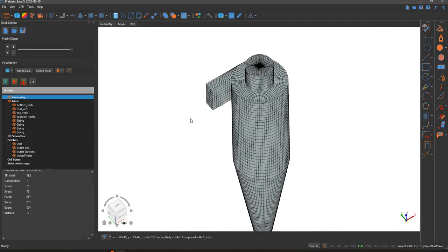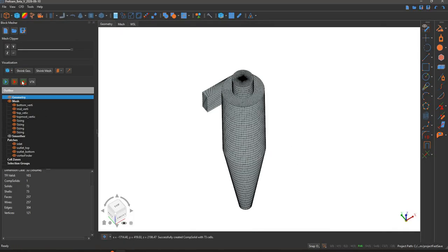So after the meshing, you can export your mesh by hitting this button. That will open a window where you can navigate to your case, and then you can export your mesh. And do not forget to run renumberMesh.